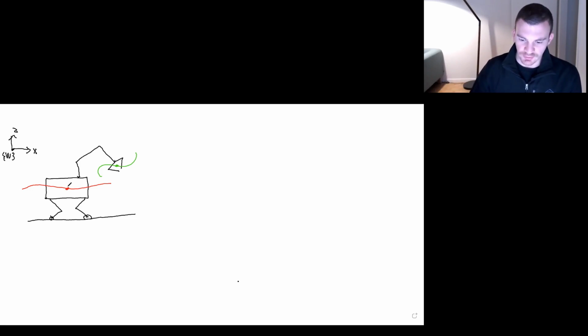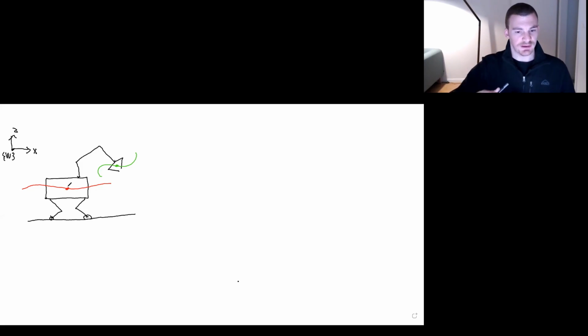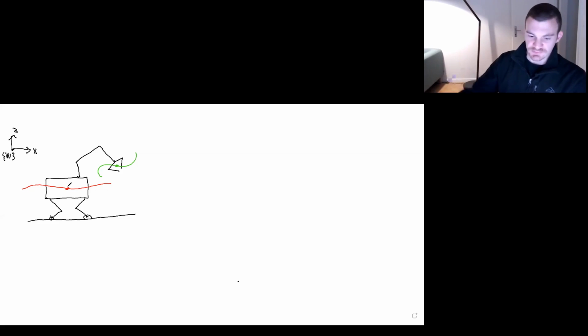Okay, those set points for us right now in this exercise, we don't really care where they come from, but you can imagine in a real scenario that they actually come from some kind of planning module that uses maybe some other model, maybe it's an MPC, maybe it's a different kind of system, maybe it's even a neural network that looks at the proprioceptive state, potentially could even look at the terrain and make this decision about roughly where to go, but then relies on the underlying whole body controller, AKA this inverse dynamics thing that we're doing, to actually execute the motion.